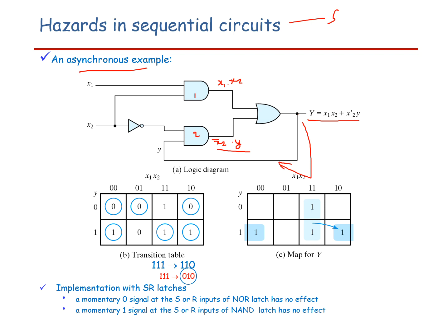Okay, so now we are going to fill it in the K map. You know that x1 x2 means both are 1, hence 1 and 1 should be filled in the concerned cell. Then x2 bar y. Here, x2 bar is these two cases, and y is these two cases, hence these two cells are filled with 1.